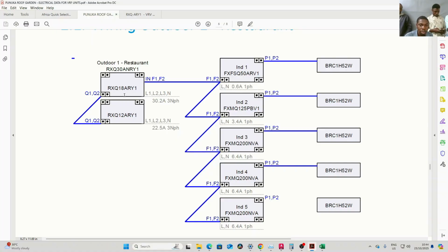What is our V, voltage? Three-phase voltage. What's our three-phase voltage? It's 400, you standardize it to 400. What's our single-phase voltage? 220 or 240. Okay, so what is our cos theta? What's the name we call cos theta? Power factor. So let's multiply it. 16, so let's just say 16.7 kilowatts.